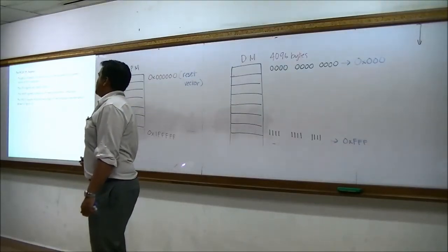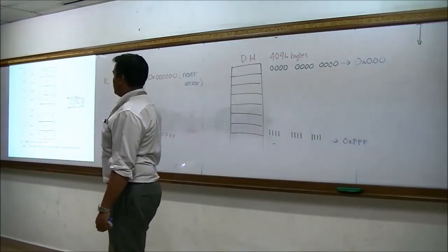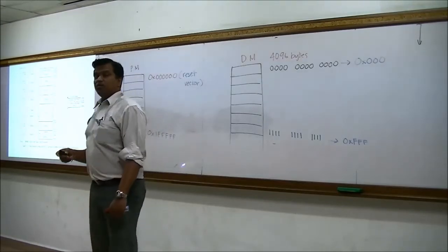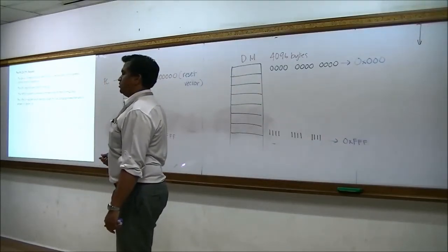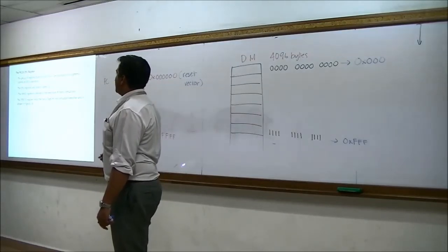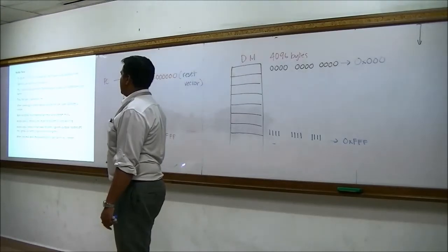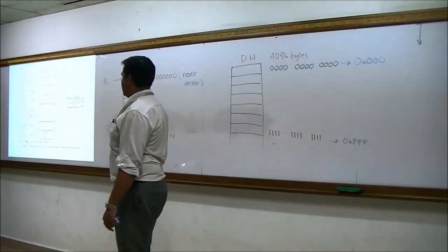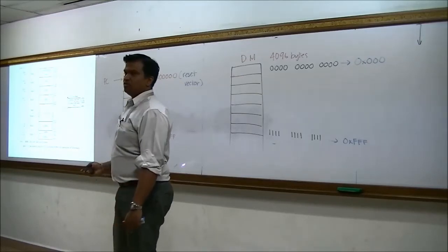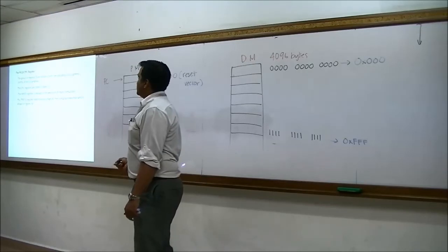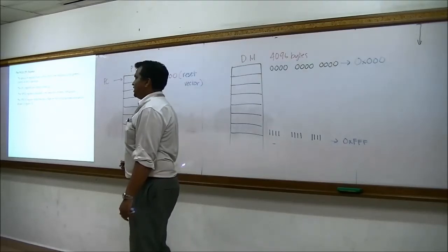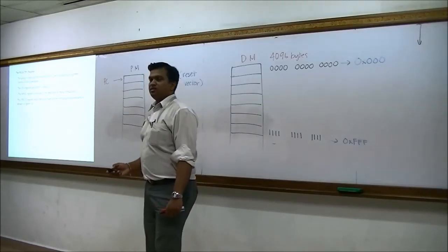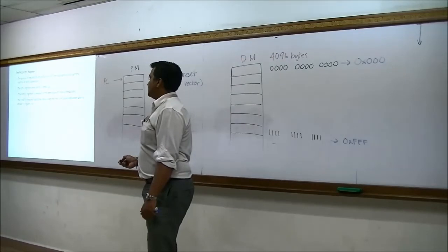Now remember that we actually saw our CPU registers. These CPU registers are also known as special function registers. Remember the earlier diagram where I said that in the CPU there are registers? That register is actually referring to this CPU register. Now the group of registers from FD8 to FFF is from here, not from F60, but from somewhere in between. So out of these SFRs, a certain portion is used as the CPU registers. They are dedicated to general microcontroller operation. Currently, the two special function registers or CPU registers that will be introduced to you are the working register and also the status register.